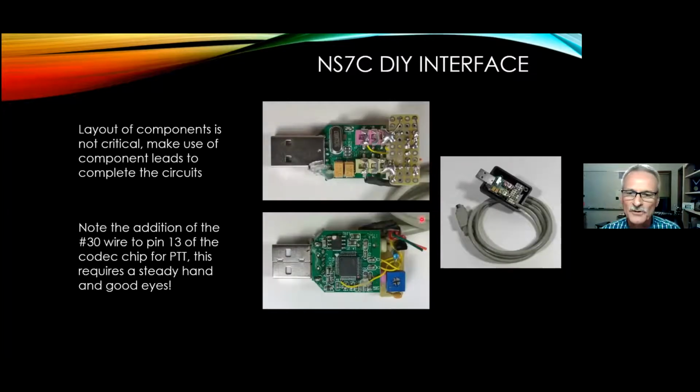Okay, so here's what the circuit looks like. I took a piece of perf board. I actually took my Dremel and ground out the other side, you can't see it on this side, so it fit the curve of these connectors right here. So it lays right up flush against the top of the connector, and then I just flowed some solder across onto the board here. So that's not only my ground connection, but also my mounting of the circuit board. And then on the other side of the board, I've got the transistor here for push to talk.